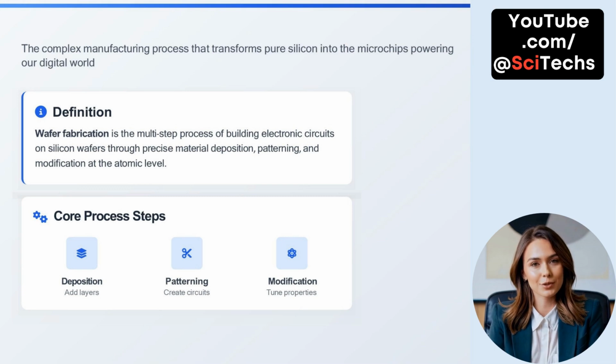Fabrication involves three essential categories of steps: deposition, patterning, and modification. Deposition refers to the addition of material layers onto the wafer's surface. These layers can be conductive, insulating, or semiconducting. Patterning is the process of creating intricate circuit designs by selectively removing or modifying parts of these layers, typically using photolithography. Finally, modification involves changing the physical or electrical properties of selected regions, such as through doping, oxidation, or annealing, to fine-tune how the chip performs. Together, these core steps are repeated many times to build up the multi-layered architecture of an integrated circuit.